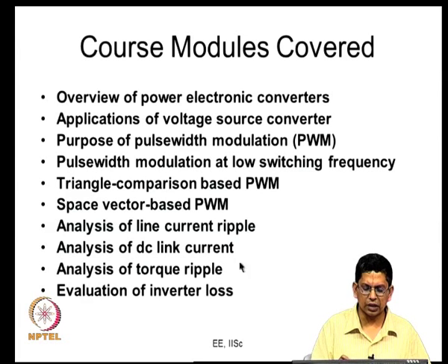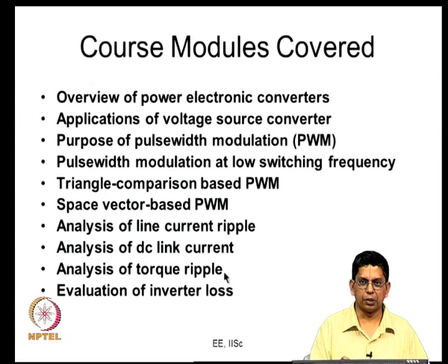Then we also did this analysis of torque ripple. We considered both the low frequency PWM and the high frequency PWM. In one lecture we focused on the low frequency PWM, looked at the corresponding flux harmonics, current harmonics and so on, and then how they would produce 6th harmonic torque and 12th harmonic torque and so on.